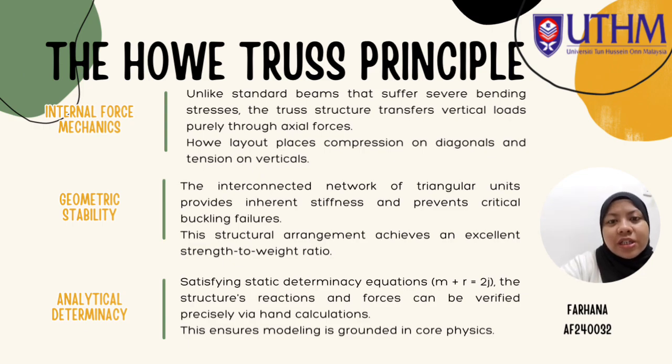forces. Traditional solid beams suffer from severe internal bending stresses when loaded. The truss, however, bypasses this limitation. By utilizing pin-connected members, it translates external vertical loads strictly into pure axial forces, meaning our balsa elements experience either pure tension or pure compression.